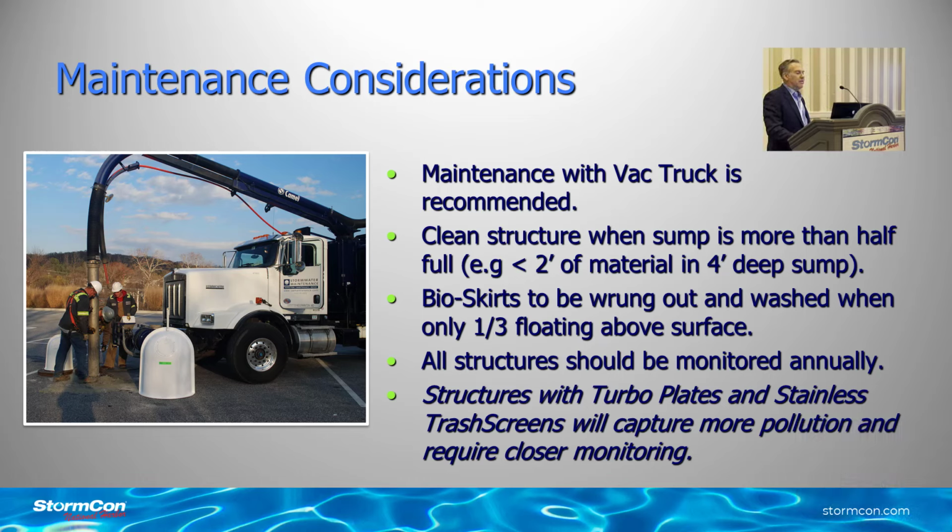Maintenance considerations are super important. When you're thinking about a structure that you're capturing pollution in, and let's say you have a 4-foot deep sump from the invert of the pipe down to the bottom, you really have about half that structure depth as useful storage. So if you have a 4-foot deep sump, you're thinking in terms of a max of 2 feet of actually being able to store stuff. Because at some point, you're going to hit a steady state where the stuff that comes in just gets flushed right out by what's coming in.